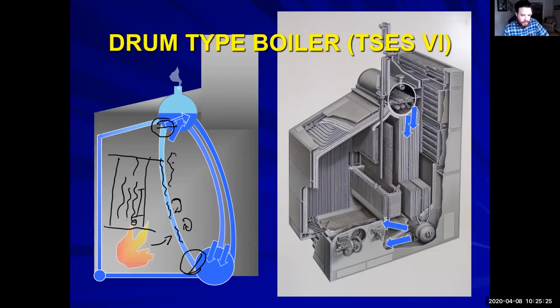And then other water molecules that are a liquid become steam around it, not only because of the steam that was inside of it, but because of the flame. And then they become steam and travel up faster. So it's just this constant process of very small molecules becoming steam, turning back into a liquid, then turning into steam again, and they're just constantly going up this whole entire generating tube that creates this flow. There is no exact point where, oh, from here to here is steam.